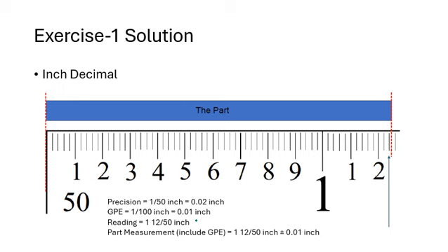For your greatest possible error, we divide the degree of precision, which is 1 by 50, that is 0.02, divided by 2, which gives you 0.01 inch. This is our reading plus or minus, and we add and subtract the greatest possible error to it, and your true length is going to be in your measurement report. Of course, in your measurement you always have to back yourself up by adding the greatest possible error that you could admit.